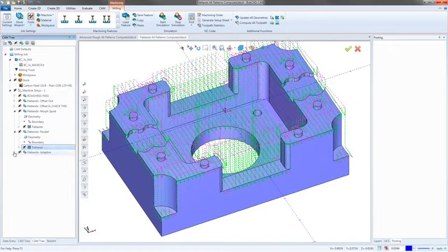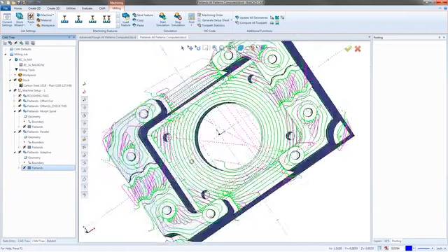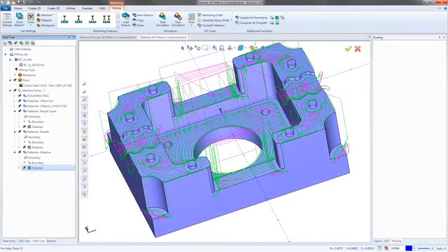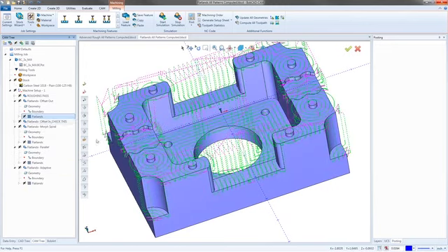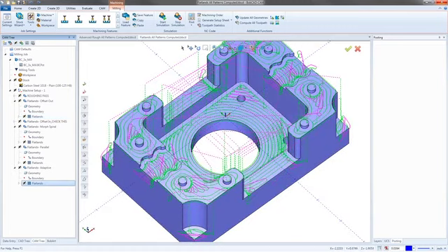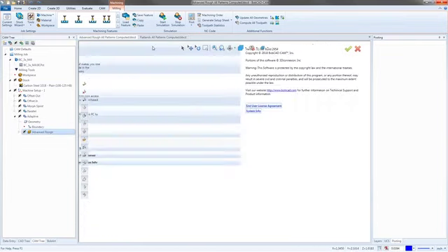I don't know. I know I copied a parallel toolpath, but the flatlands is working for the adaptive. That's the adaptive flatlands. The only problem with the adaptive is in some of these areas like here, depending on your step over and everything, you sometimes end up with a lot more toolpath than you might really need. Like the offset out doesn't have 20 cuts down the middle of this like the flatlands down here for the adaptive, but you can definitely play with some of the options, tweak things, especially the step over amount. That's always going to make a huge difference. And yeah, like I said, I'll fix these other ones and show you guys a sample of it next week just so we don't waste some time on it.